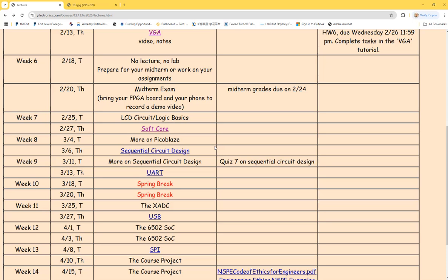That is why FPGA is so popular. It is also an ASIC, just a little bit more expensive than totally customized integrated circuits. If you're only selling 10 or 20, FPGAs make sense, but if you're trying to sell 100 million, then definitely the digital ASICs will be more profitable.